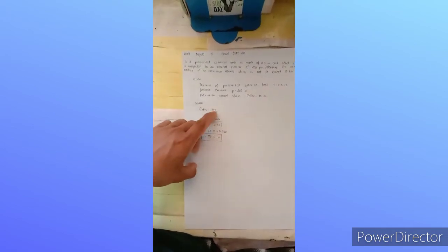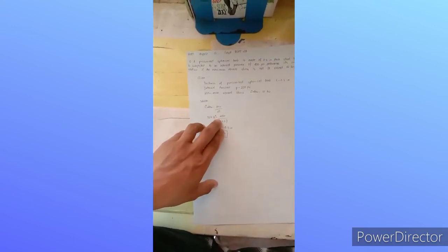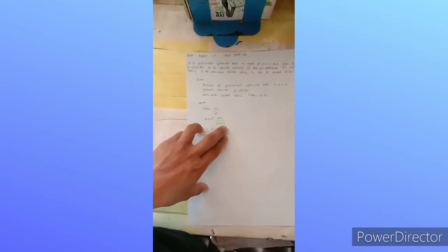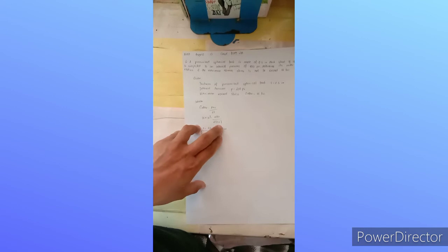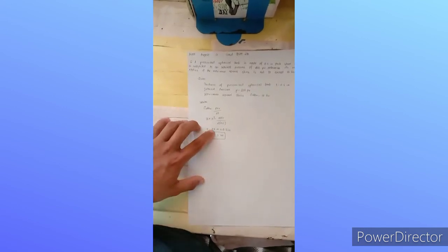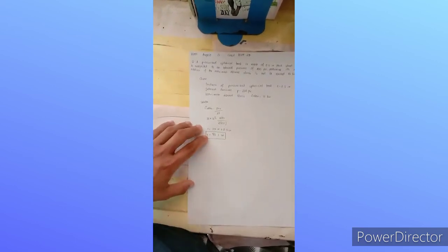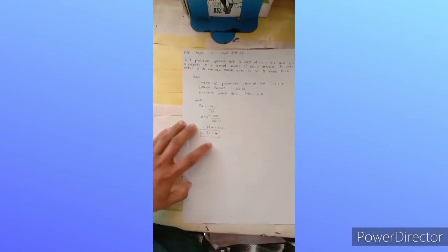So solution, allowable stress is equals to P times R all over 2T. So 15 times 10 raised to 3, which is our allowable stress, is equals to 200 psi, our external pressure, all over 2 times our thickness, 0.5. Our R is equals to 75 inches plus 0.5 inches. So in total our R is equals to 75.5 inches.